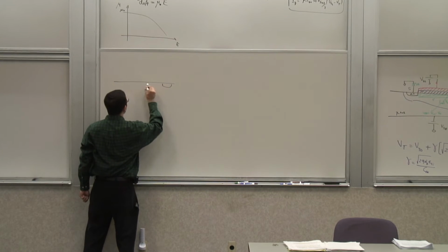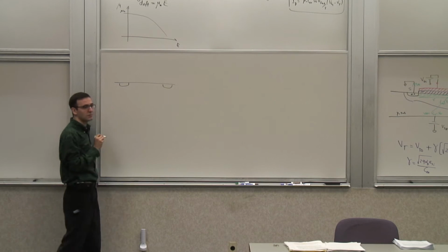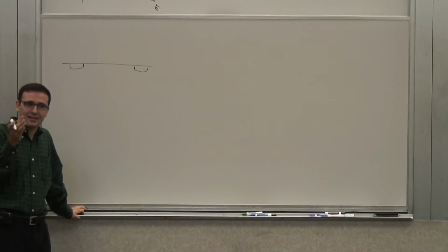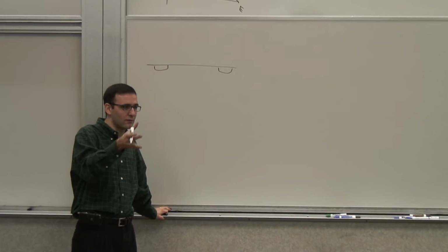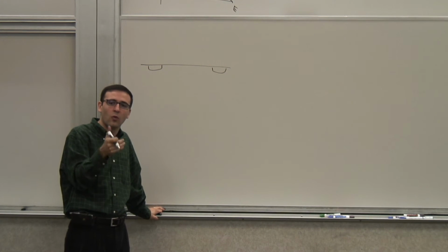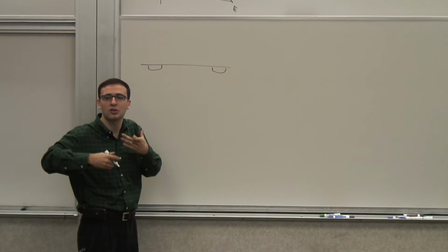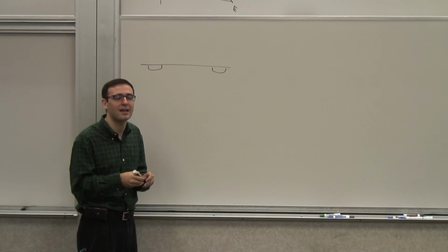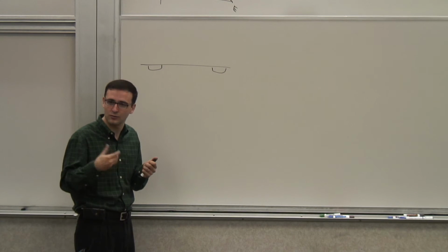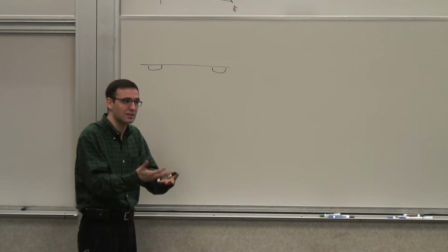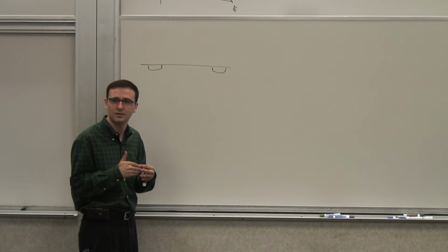Now, think about our discussion about the threshold voltage of the MOSFET and the MOS cap, right? There were several different terms in that expression for the threshold voltage, and they accounted for different things that the voltage on the gate has to account for. One of the things was to compensate the electric field generated by the depletion region. In other words, to create the depletion region, you need to have a certain amount of VGS first. You have to apply a certain level of voltage to the gate to create first the depletion region, and then you could go to inversion.